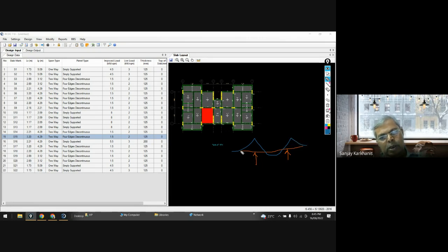Right. So here it is 0. Here it is 0. Here it is max support. Here it is max. Then here it is a contraflexure. That means point of 0 bending moment. Here it is point of 0. So only in this part, theoretically, I need a reinforcement to be provided at bottom. Right. And only in this part, I need a reinforcement to be provided at top.